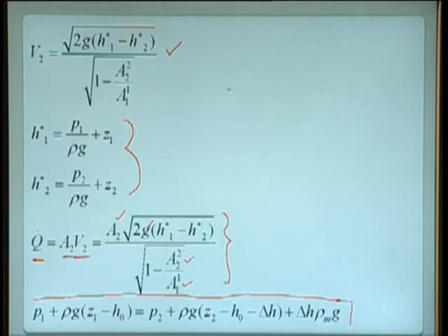Suppose we have 2 points which are connected to this U-tube manometer. And here since pressure was more, it will compress up to this point, and here it will compress up to this. So, this is manometric fluid having density gamma 2, and here we have a fluid having density gamma 1. This is connected to throat and this is connected to inlet of the pipe.